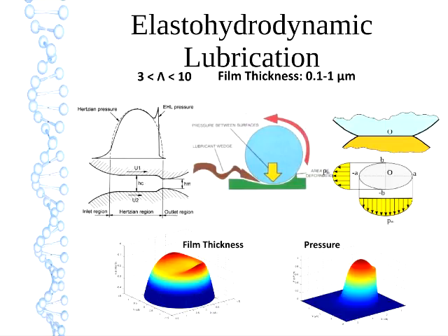But you can see here that the low film thickness area extends around three sides of the contact. The area where the film thickness doesn't drop is the inlet, and same, that pressure spike kind of curves around the side. So this is classical EHL pressure and film thickness shapes.